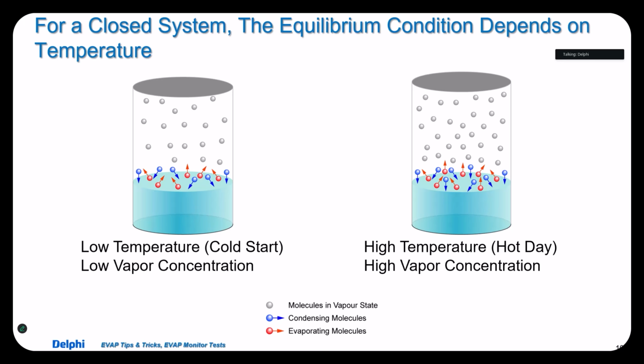For most cars, they're doing that through the FTP, the fuel tank pressure sensor and the voltage that it implies. For the Nissan I'm going to show you later, they have a temperature sensor in the tank, and that's going to be the key to running Nissan EVAP monitors. The disadvantage of that is, because it's so temperature sensitive, depending on the environment you're driving it in, if it's a cool day, it would take quite a while to get that temperature up to where the system will test. I've had them go on hot days where it only takes 15, 20 minutes, and I've driven them on cold days where you could drive for many miles before that tank will get hot enough to build up the pressure to do the testing.